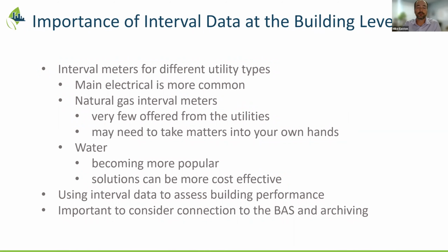Yeah, Mike, if you're going to be installing a main natural gas meter or natural gas sub meters, what you want to do first is understand what your application is. In some instances and for some municipalities, we're doing billing applications where they're metering tenants in their space. If that's the case, it needs to be a Measurement Canada approved meter, because Measurement Canada regulates natural gas in Canada. So you're limited to an inline diaphragm or rotary meter that needs to be sealed and commissioned in the field.